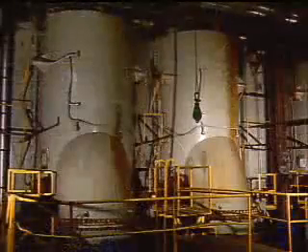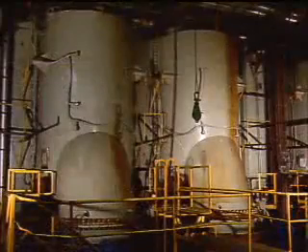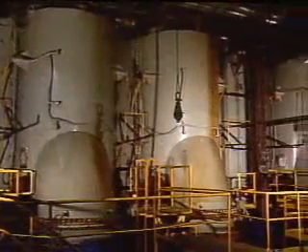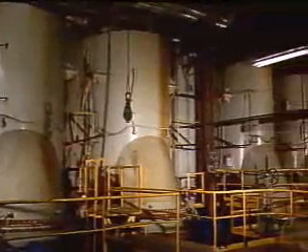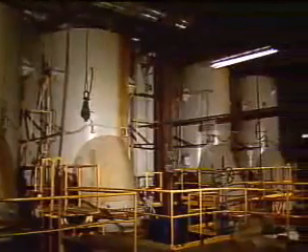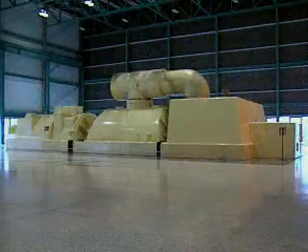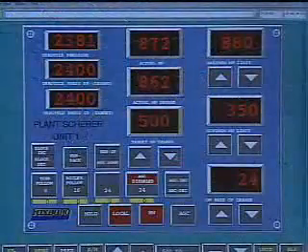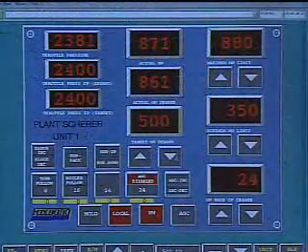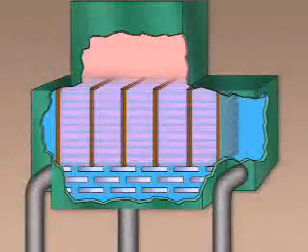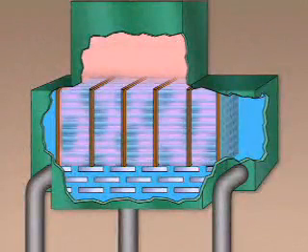For instance, if there is a severe tube leak or blockage in one half of the condenser, that half can be shut down for repairs while the other half remains in service. That way, the turbine can continue to operate while the condenser is being repaired. Keep in mind, though, that load may have to be reduced during the repair since condenser capacity is less than before.